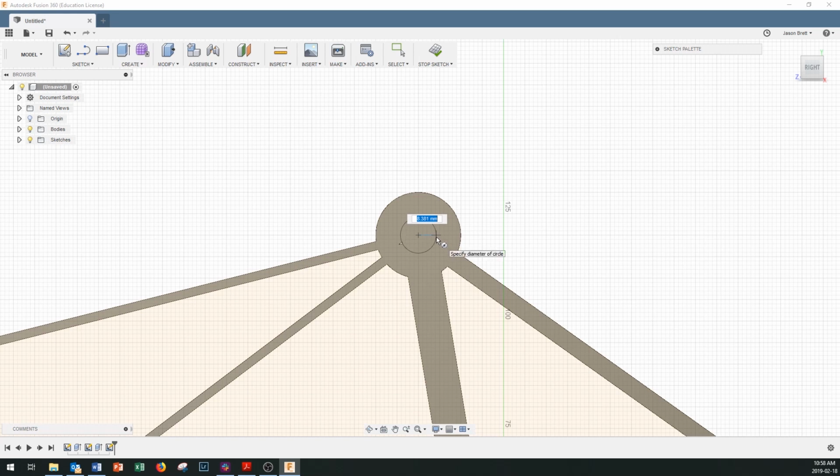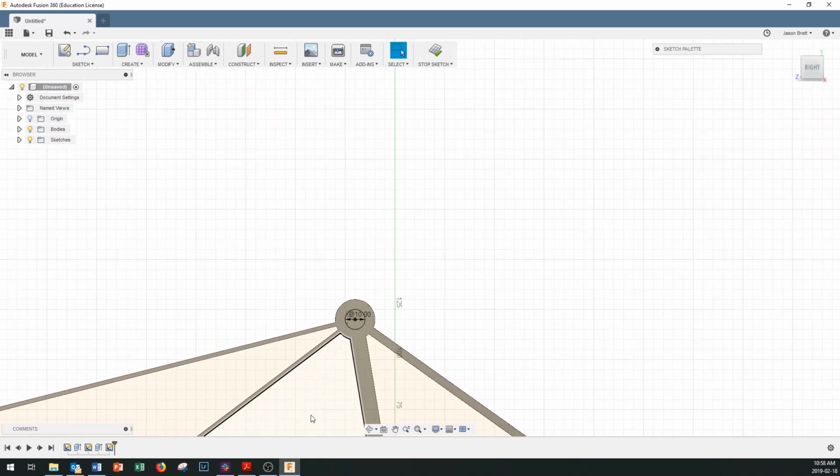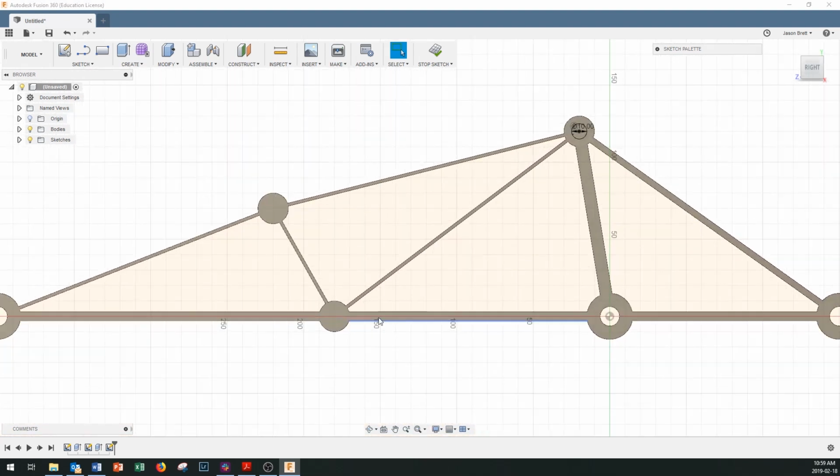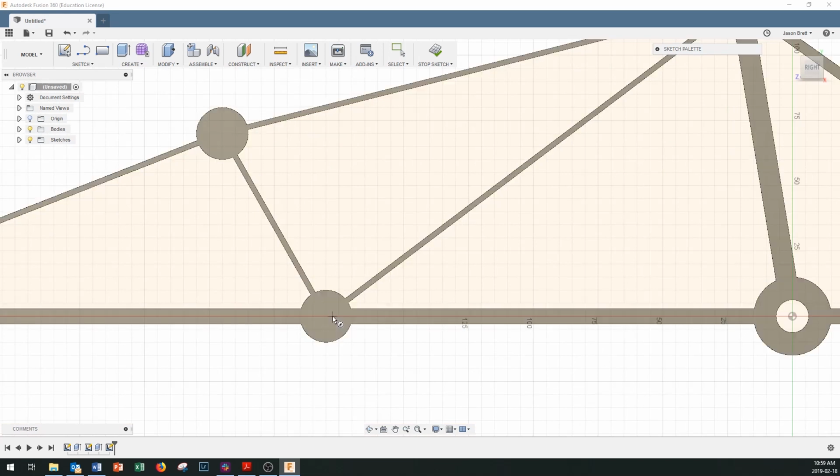If you're using, let's say 1/2 inch dowel, that'll be 12.5 millimeters. 1/4 inch dowel is 6 millimeters. But to be nice and metric, I'm just going to put in 10 millimeters and assume you've got some nice round piece of 10 millimeter material that's going to extrude right across there. And we'll fit this in right here. And again, circle. And we'll come in right there. 10 millimeters. Press enter a second time, make sure that fixes in there.